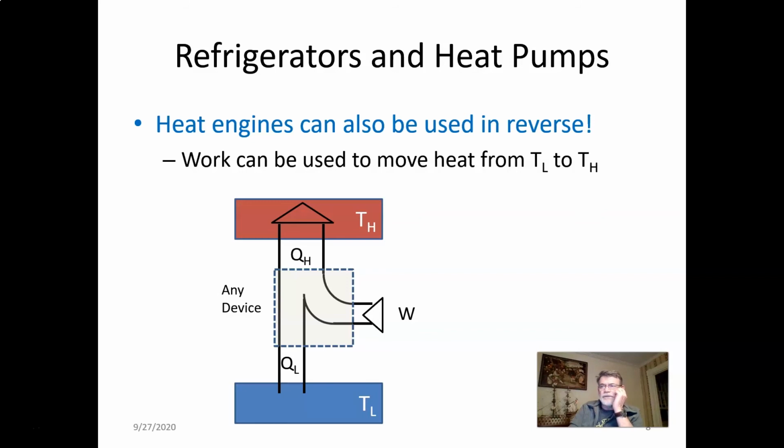So the most common refrigeration cycle, which is valid for heat pumps and refrigerators, which are basically the same machines, is the vapor compression cycle, which uses refrigerants like Freons that change phase. There are other gas refrigeration cycles like the reverse Brayton cycle, the same one as the gas turbine but reversed, or, for example, the Hampson-Linde cycle.